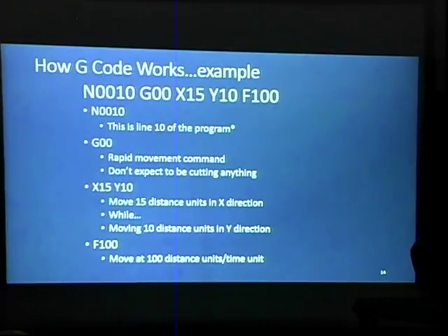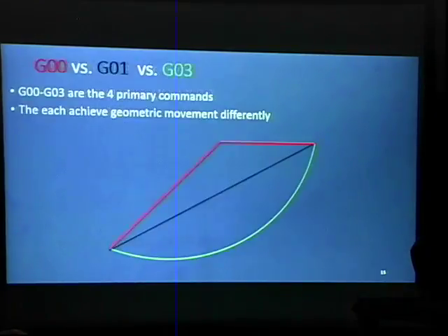It's able to implement that because the reality is when it implements these different commands, it's taking that code, which again is more like an API. It's bringing that code in the controller and it's processing it down to a physical action on the tool. That physical action on the tool is going to exist in stepper counts or servo motion. It's counting out how far it's going to move to achieve the distance that you asked it to, and those numbers are going to be very different, and machine specific.